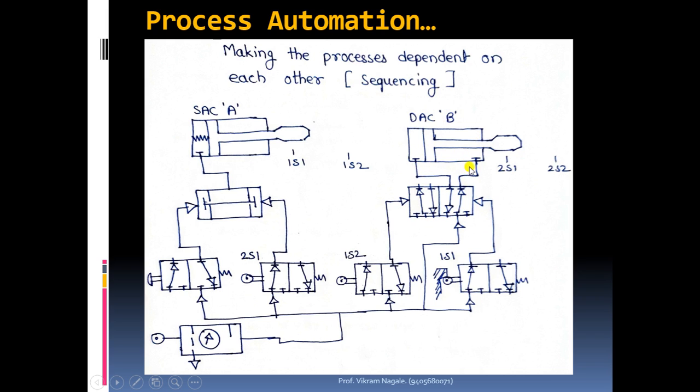These are the two input ports for the double acting cylinder. Now I said that there are two ports on the output side, because here although four are visible, those four are for two blocks, for two positions. How many are there at a time for one position? Two. And that will coincide with the ports on the casing for that valve. So how many ports are available on the casing for actual connection? Only two. Okay, that will be connected in such a way that left to left and right to right.